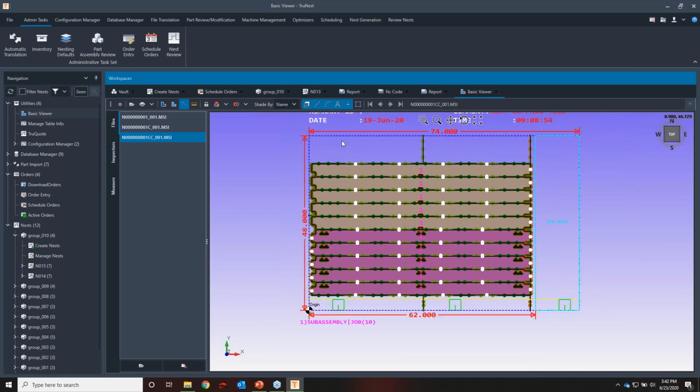We're using less of the material up top here, so we could potentially fit, you know, 1 or 2 more parts as well on the sheet. And we're saving close to 10% now from the original nest, about 65, 70 hits in this particular case. So all those savings add up over time, over nests, and really contribute to an ROI, things like that, for automated solutions like TruNest. So I wanted to show that off.